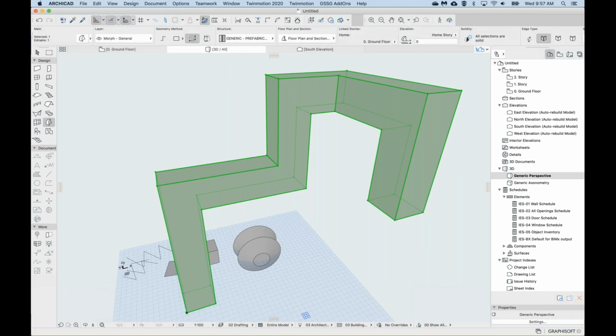Remember when we started at the beginning, we could see when we hover over the X, Y, or Z, they would turn yellow. As soon as they turn yellow, you can hold Shift and it will lock to that axis. I find that's the most useful method to get this tube. If you have a wall or something, then obviously you can trace with the points of the wall. For example, if you want to do some architrave type work around a doorway or some moldings.